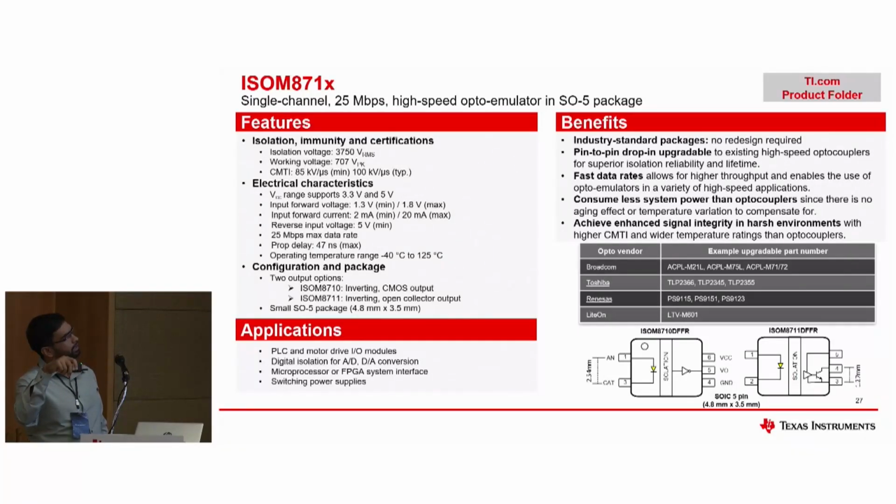And the prop delay is well within 15 nanoseconds, which is again best in class, and it is reliable over lifetime for tri-temp operation. And these are some of the part-to-part replacement devices, which if you compare the data sheet and the specs, you will find the difference in what we are talking about.